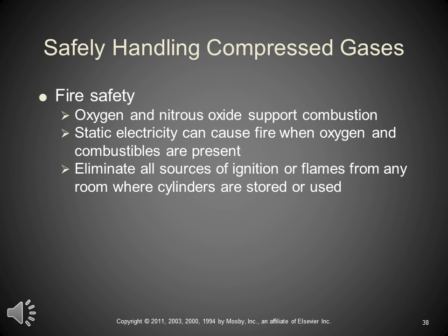Certainly, we're going to be handling compressed gases. I need to be careful with these guys. They're dangerous. There is a fire safety issue. Oxygen and nitrous oxide will support combustion. They burn and they blow up. Static electricity can cause fires when oxygen and combustibles are present.